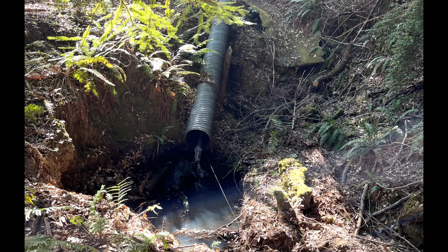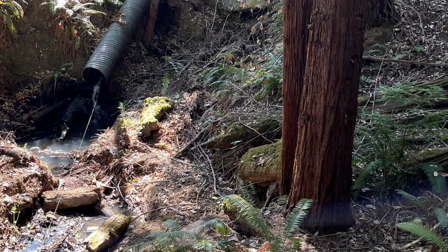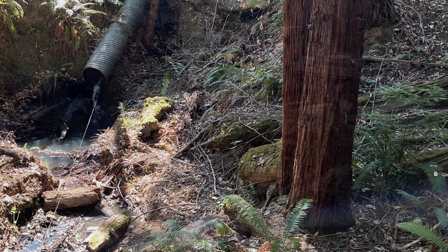When Gabrielle acquired the property, she and her partner Dan observed that the spillway for the pond was eroding. A pipe that was too small in diameter had been used to carry water over the dam. Water flowing out of the pipe had washed a chunk of soil out of the dam. During a flood, water would flow around the pipe, causing a head cut to form in the backside of the dam. Gabriel and Dan wanted to take action to rebuild the spillway before the dam washed away.